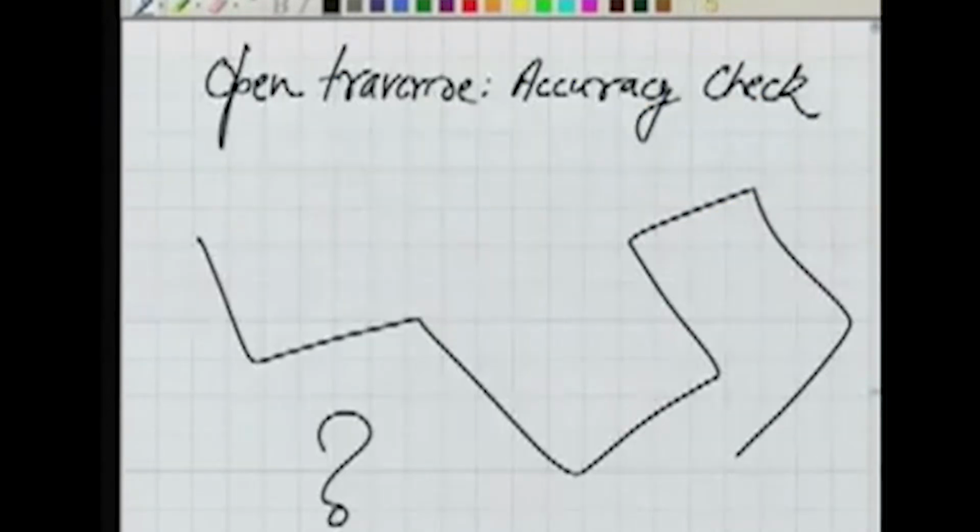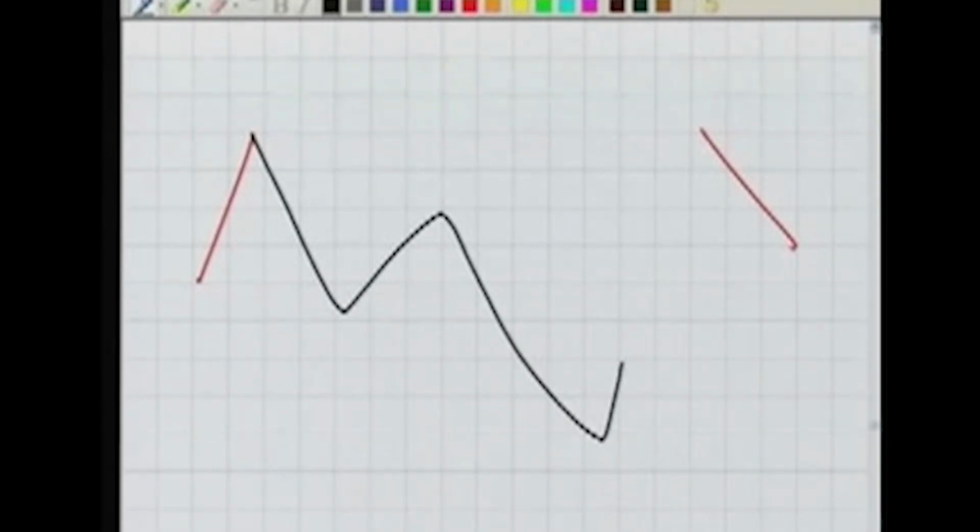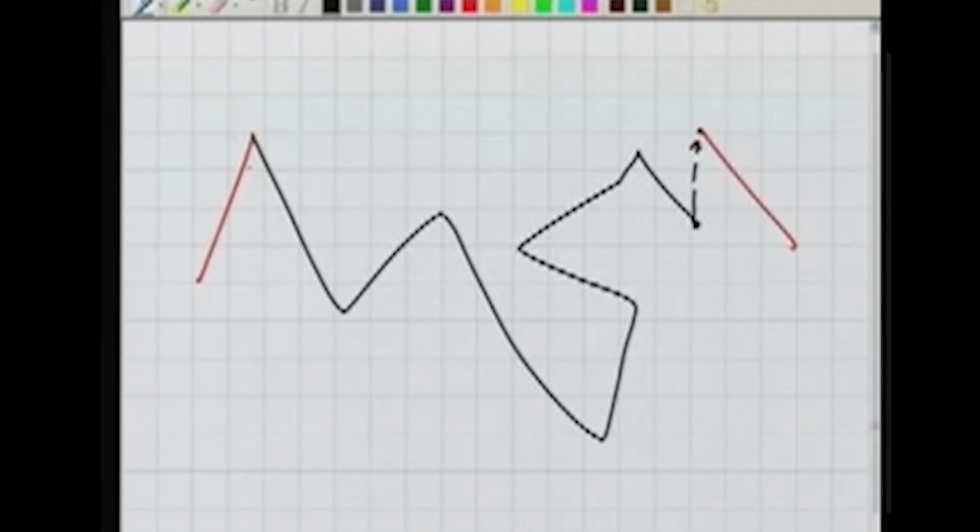So this adjustment procedure could be, let us say, if this is our link traverse and it does not close here, as well as it computes the bearing wrongly. Let us say I am taking the case that it does not close here. Closing means I had done a traverse in the field and now I am plotting it here, using these angles and the lengths, and I find that it does not close.